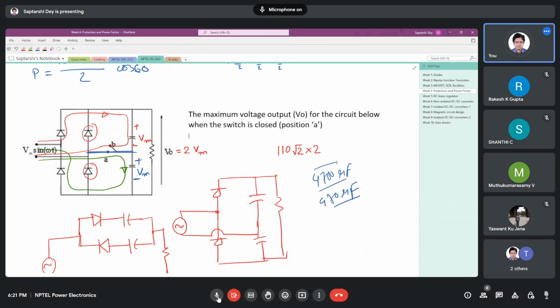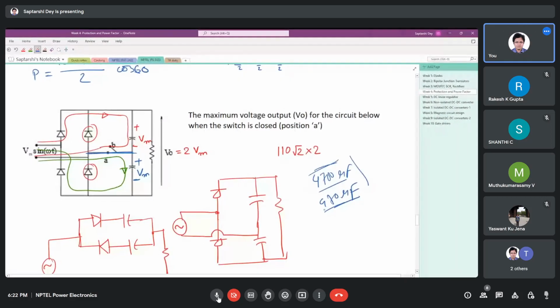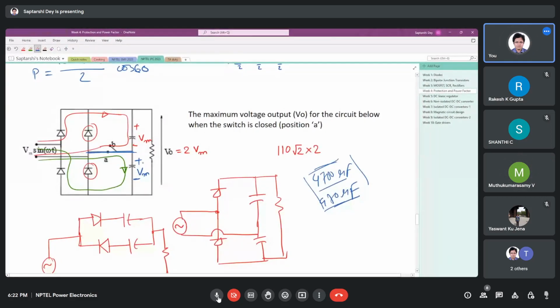And even if you get these ceramic capacitors, I mean these unpolarized capacitors, of this much capacitance value, most probably you will not get it at the voltage level that is required. See, this rectifier is connected to the grid, so you will need something that can block at least 200 volts, since two are in series, maybe even more.